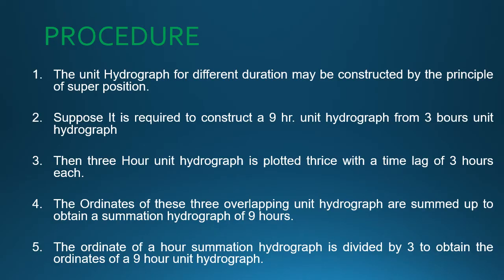Now, the procedure of finding out the unit hydrograph of a different duration from a given unit hydrograph can be attained by the principle of superposition. That is, we can construct a 9-hour unit hydrograph from a 3-hour unit hydrograph, or a 4-hour unit hydrograph from a 2-hour unit hydrograph. We can do these things by the method of superposition, and